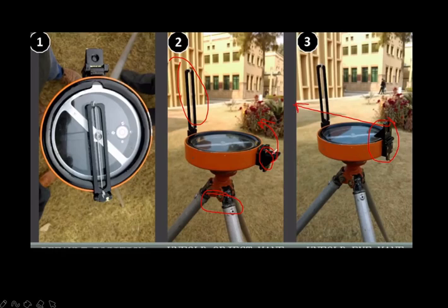Okay, so in this the prism will be there. On this graduated ring, the numbers of the bearing are written mirror-wise. If 10 degrees is written mirror-wise, it appears as 01. If 20 is written like this, it will not be written as 20, it will be written as 02, mirrored. So the mirror image of the numbers will be there on the graduated ring. It will be corrected by the prism. So when we see through the prism, we will directly identify the degree.